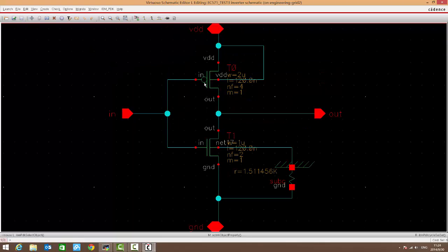okay, I'm going to save this. So this has 4 terminals, 4 nodes, and we're going to package this into a symbol. A symbol is like a black box, and we can only see these 4 nodes outside the black box, and we cannot see what's inside unless we descend edit into this. I'll show it later, and this will provide a cleaner look of our circuit.